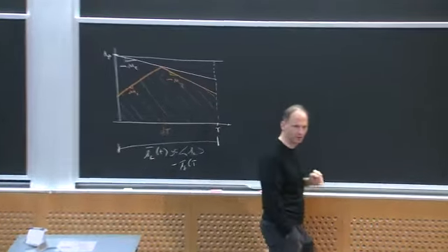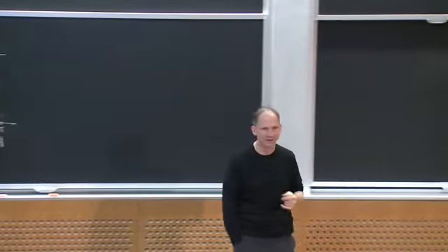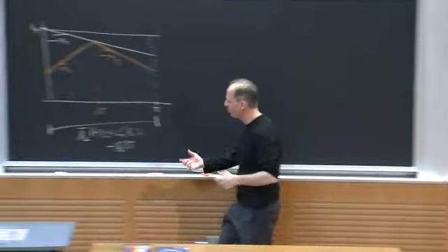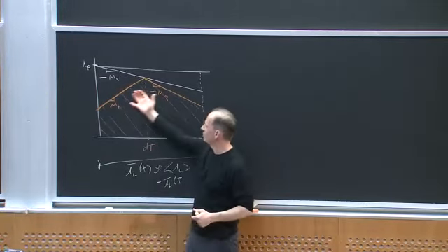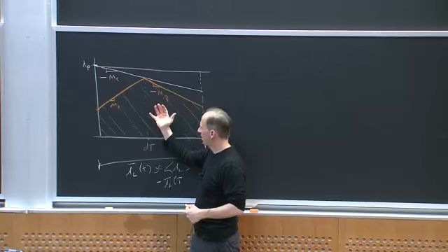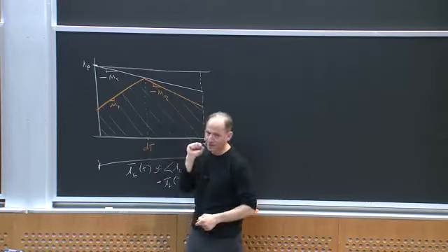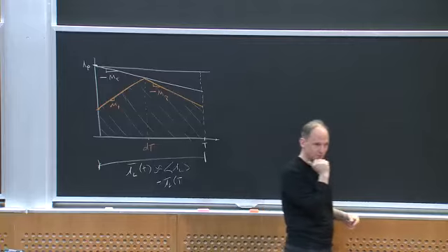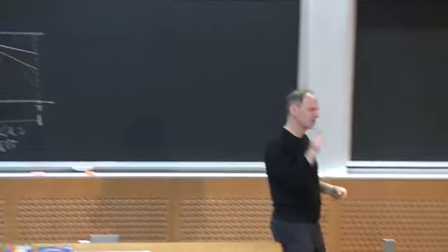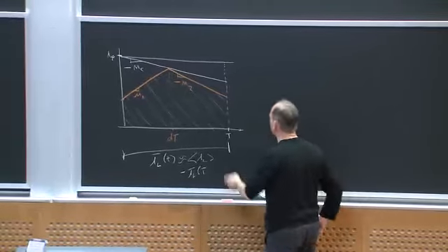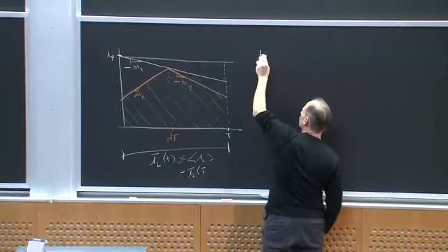But do people see the basic idea I'm going to use? I'm going to approximate IL bar as the average of this waveform, and then that's a function of the duty ratio in that cycle, and then I'm going to swap that into my local average duty ratio equations. Okay. Actually, I'm going to linearize it first, but that's neither here nor there. So let's do that. What is my approximation to IL bar?